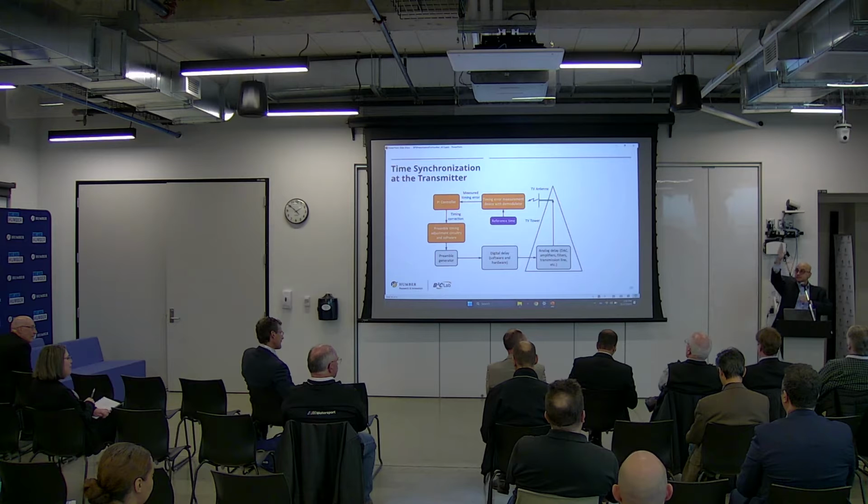You're listening to the real transmission. Using a reference time, we measure the error, and we feed back the error. We ask the system to adjust. If it's 20 nanosecond early, you have to tune a little bit, a couple of loops, and it'll adjust to 20 nanosecond. So that is actually the synchronization loop.